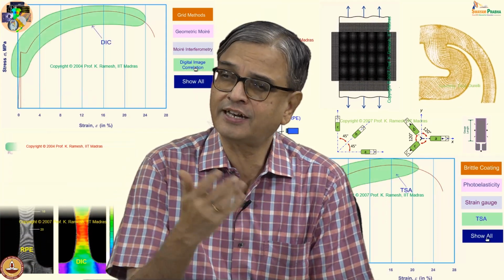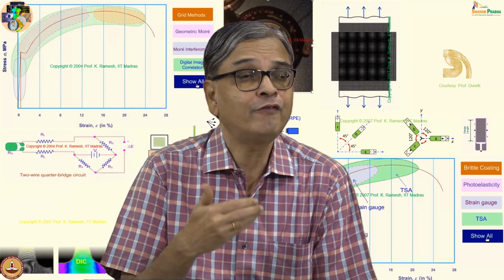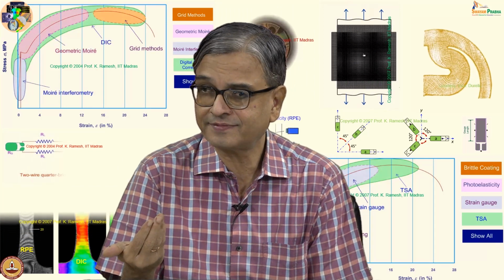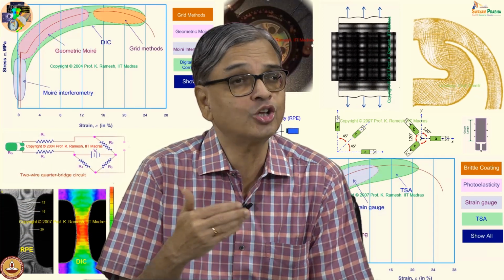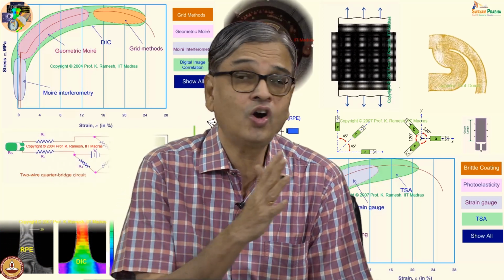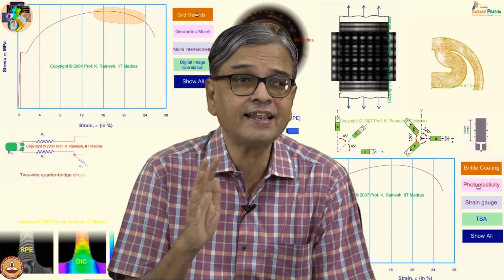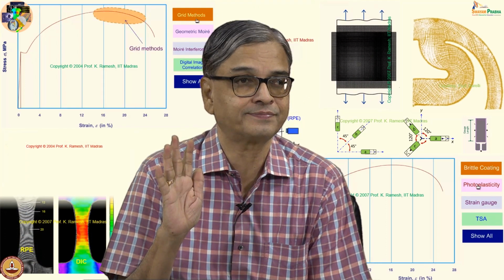When you stretch a conductor, whatever the stress introduced influences the change in the resistance, but the resistance change also can occur because of change in temperature. So, in all strain gauge measurement, you must account and segregate any effect due to temperature.